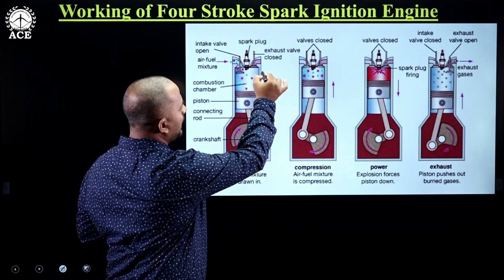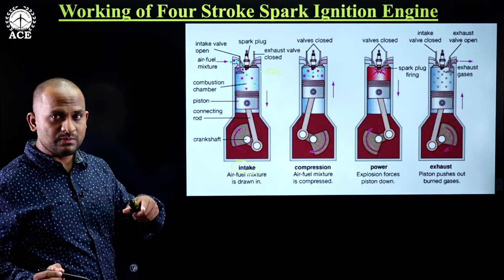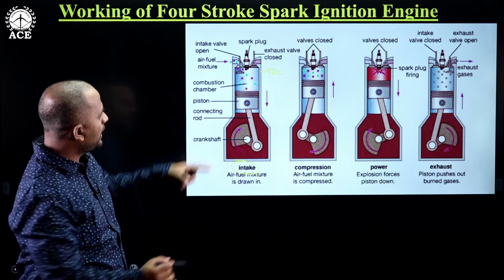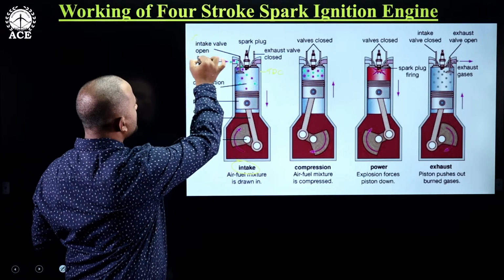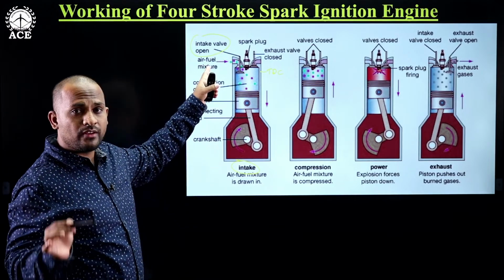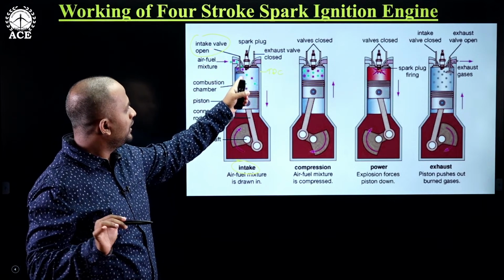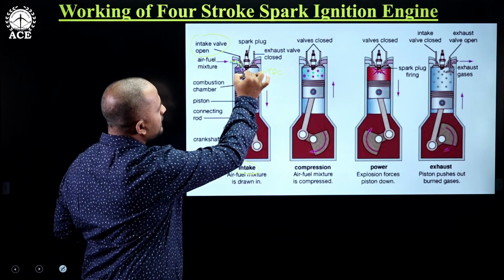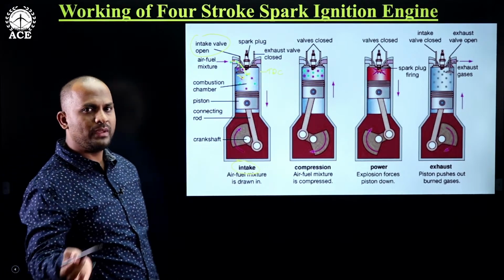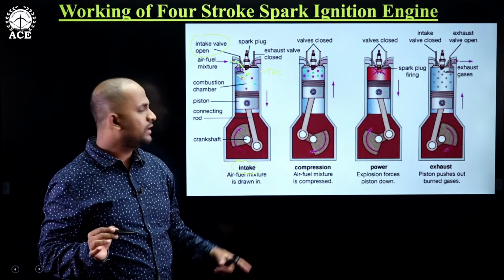When the piston starts moving from TDC to BDC, the inlet valve is opened, and the air and fuel mixture enters the cylinder through the inlet valve during the intake or suction process.